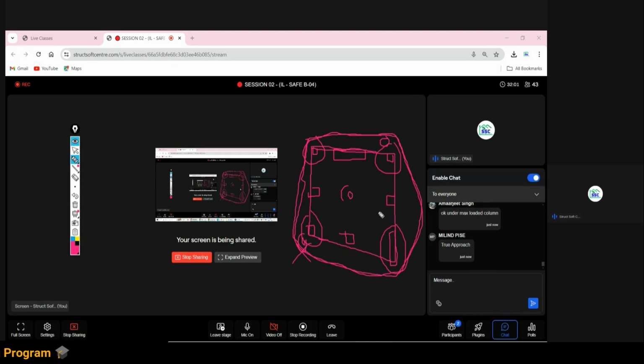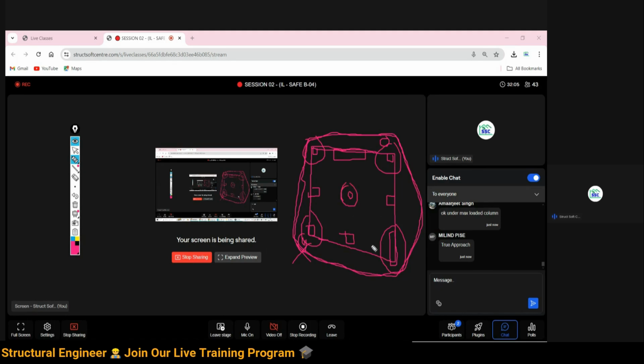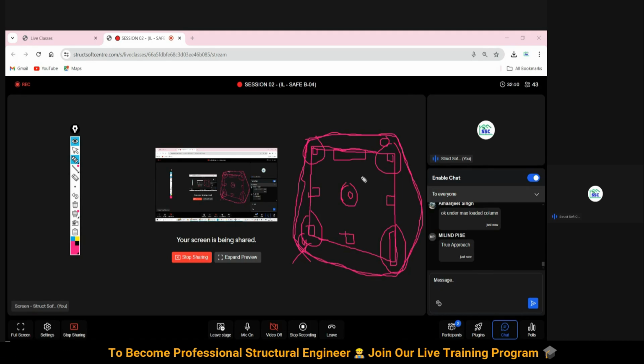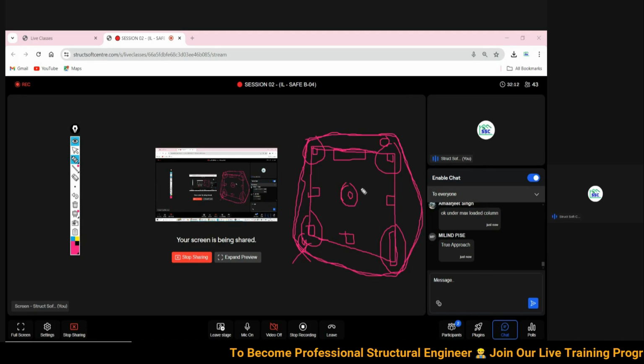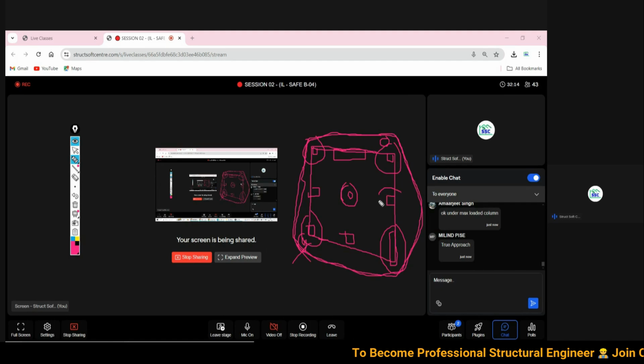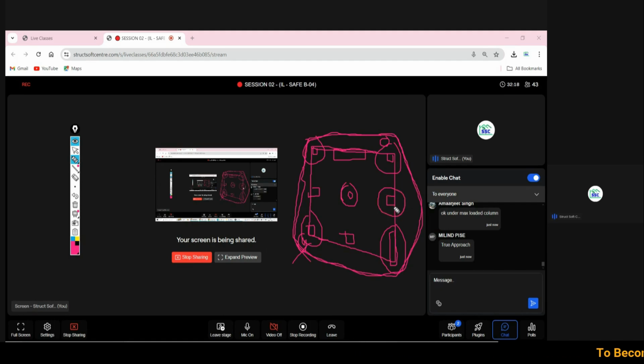But in addition to this, the sixth point at the center is also going to be performed. They want to know the sixth point. So at the sixth point, they are going to check where the maximum gravitational load or point load is coming. Suppose this is the point, so they are going to choose this point for the sixth borehole. So this is one approach in a critical situation. This practice is followed by practitioners.